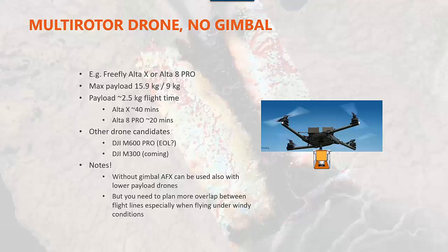So without the gimbal, the AFX can be used with the lower payload drones. But when you don't have the gimbal, you need to plan more overlap between flight lines, especially when flying under windy conditions. So you need to pay attention to that.